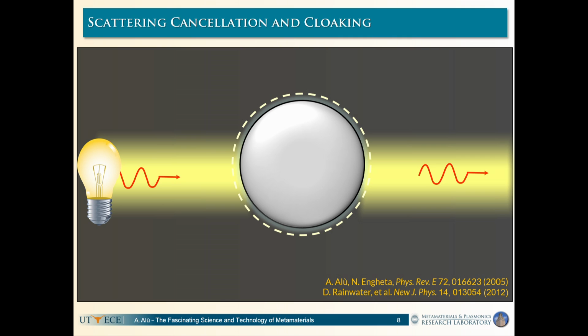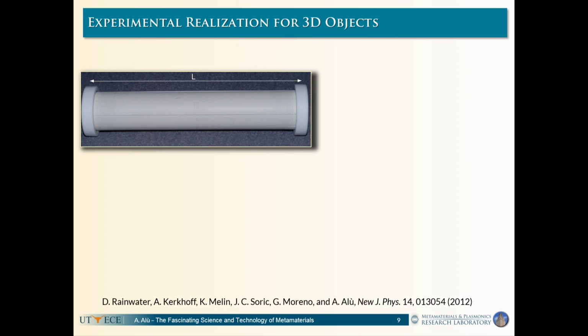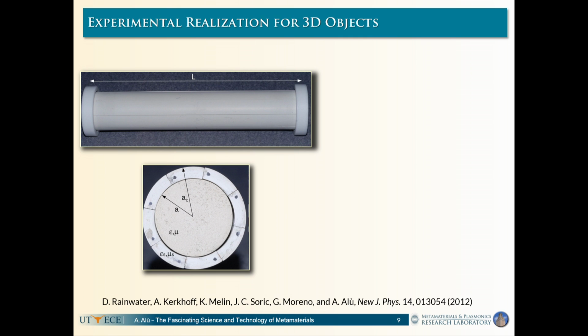And in fact, over the years, we've worked on metamaterials mostly for radio wave frequencies, so lower frequencies, longer wavelengths than light, that allow you indeed to scatter this negative phase light. We call it scattering cancellation. This, for instance, is an example of a material that is made of these metallic implants embedded in a high-permittivity ceramic shell.